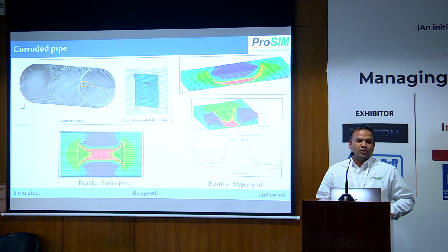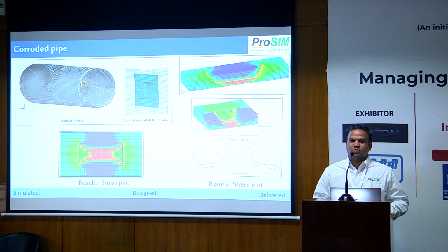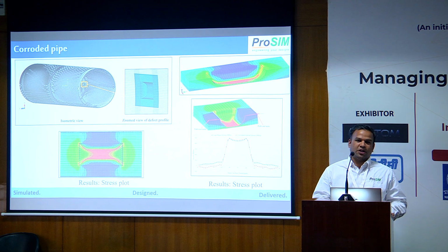So here, SCC, this morning sir was explaining stress corrosion cracking. When there is a sustained stress on the material and an environment that calls for corrosion, or it may be a strain rate, that will call for fatigue. When the strain rate and stress combine with the environment, it is corrosion fatigue. When there is a combination of degradation, it is called stress corrosion cracking. So if you look at SCC in a pipeline, it is not shown here.